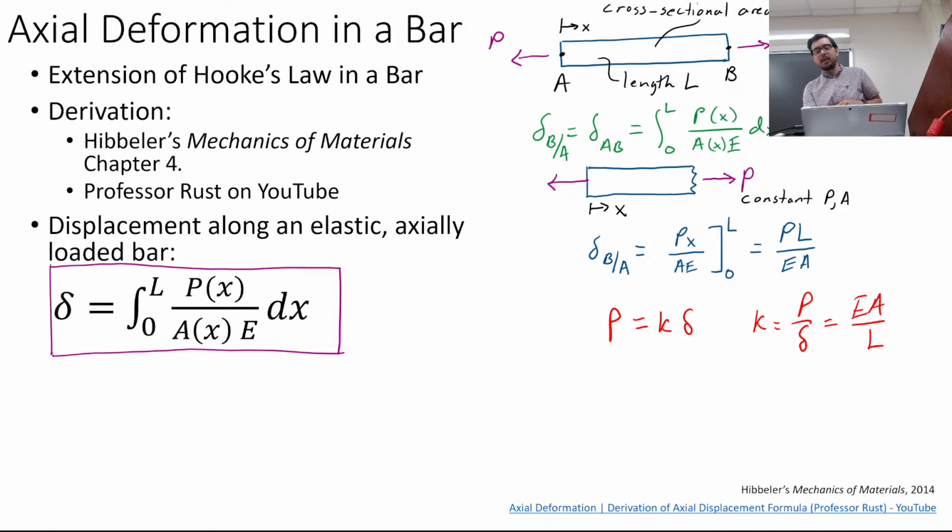And that's how I was calculating the Ks. So you can remember this equation, or you can remember that equation, or you should probably remember them both. Because as a mechanical engineer, you'd say, oh yeah, that's just FL over EA, and now I know how much the bar is extended.